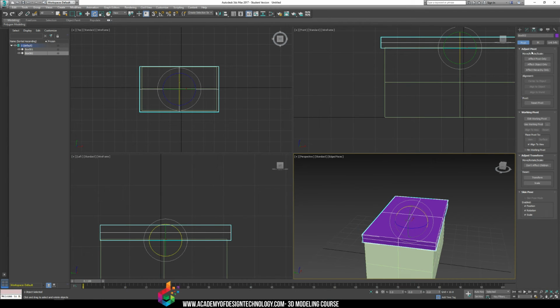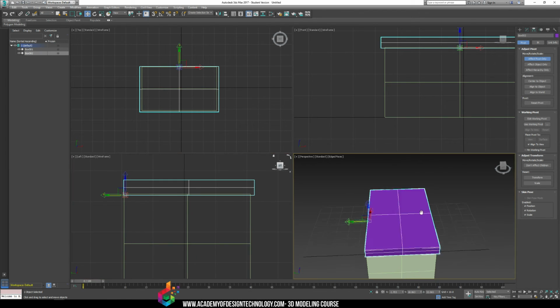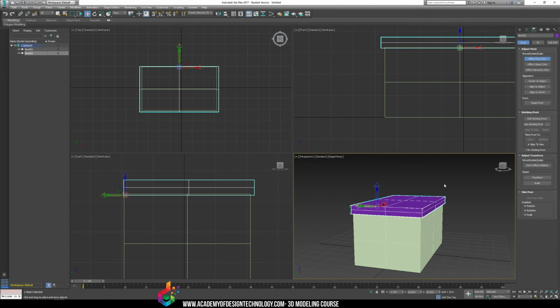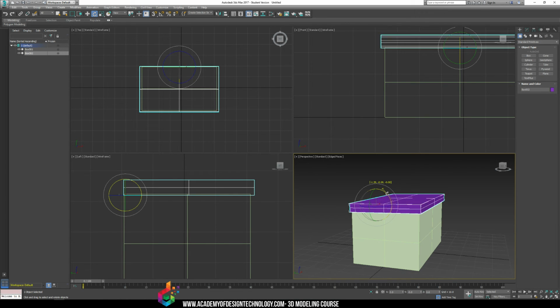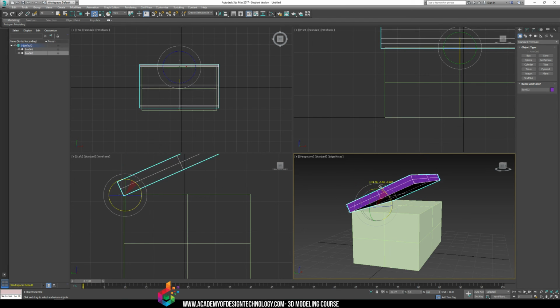If I change the position of this pivot point, however, to exactly where the pivot point of a chest top would be, so moving it all the way back, say about here, oh, wrong location, sorry, the back of the 3D model, which is about there. I look at my left view, sorry, apologies, I looked in the wrong view. I move it to the back of the 3D model, where I think it'll rotate. It should rotate as being a treasure chest top. I then use the rotate tool, and now we get a proper chest opening and closing.